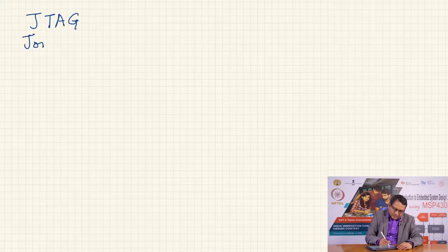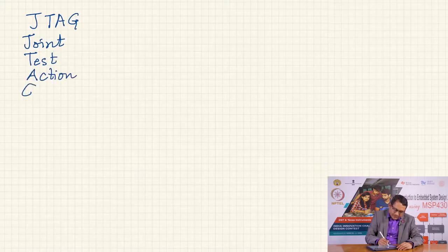JTAG is the JTAG interface. It stands for Joint Test Action Group. It is the name of the protocol. It is a 4-wire serial protocol.